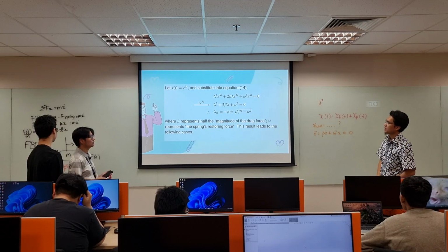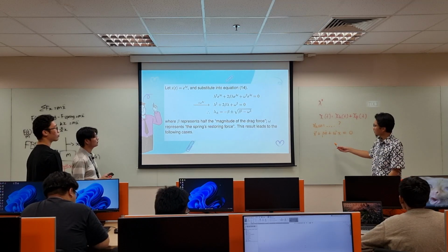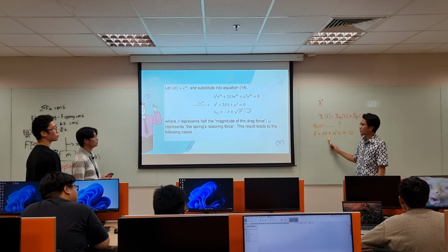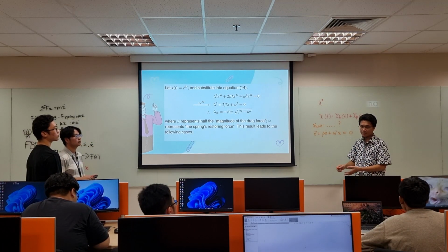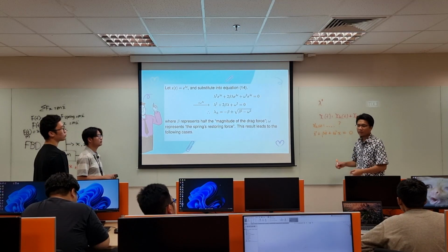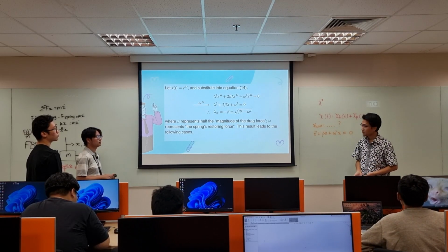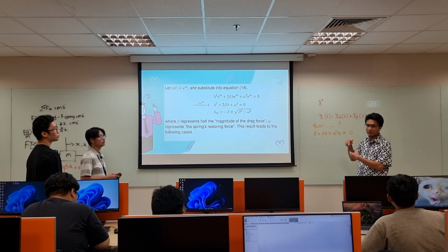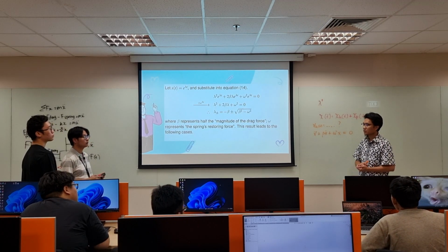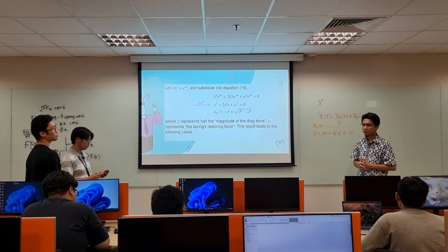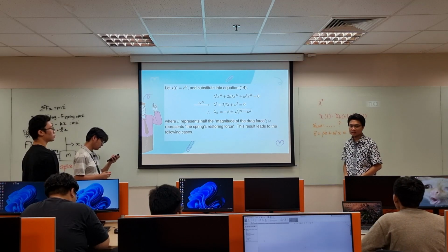Okay, sir. To make it quick, because we have damping here, the homogeneous part will eventually go to 0. This is a transient part, whether it is weakly damped or underdamped, critically damped or overdamped, the homogeneous part will eventually die out. And so this is why we are not showing the homogeneous solution for the case of a periodic function as the force.